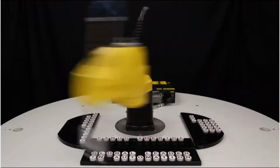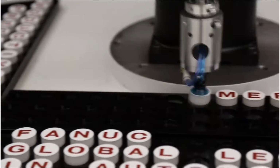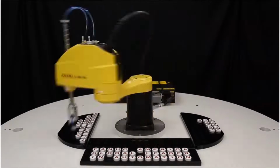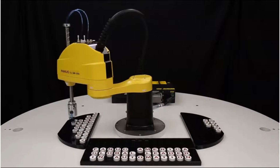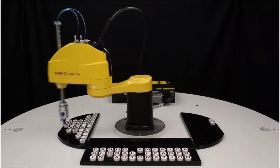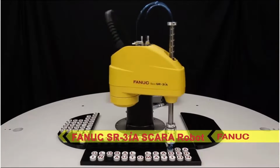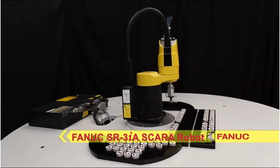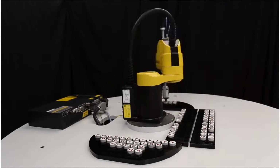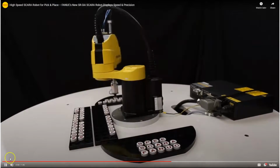All right, so you can see in this example, the SCARA robot isn't moving with a great deal of flexibility or distance. Its work envelope is rather limited, but it is able to fly in its motions. So it's very fast, it's very controlled. It's also very stiff, which is important, right? It's not flexible, which is good. When you're moving at a high speed, you don't want a flexible robot. A flexible robot at high speed is going to introduce a lot of imprecision, inaccuracy in its motions. All right, so there's our SCARA robot.